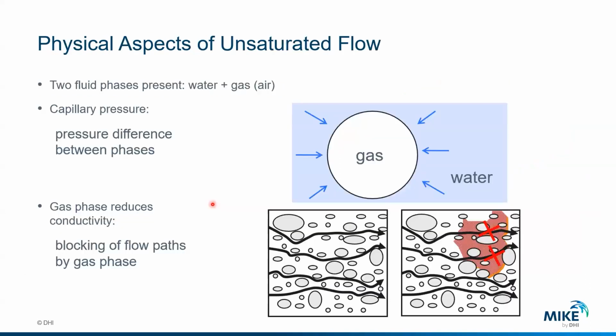When we talk about unsaturated flow, if we remember our hydrogeological classes, we used to explain this with three phases: soil, a solid, a gas, so a void space, and a space filled with water. So we talk about multiple, let's call them compartments, to explain it simply. But we don't want to simulate these compartments separately because we'd basically be overkilling the numerical calculation. It will take more time to do in multi-phases. So we simplify this by having one single phase.